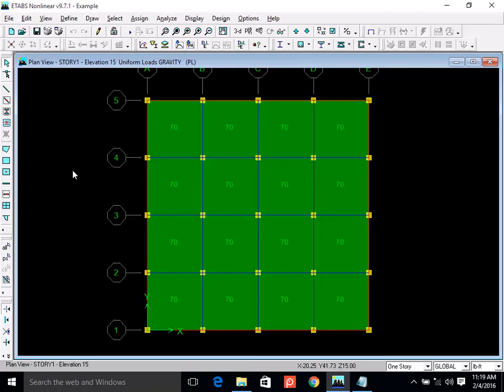You calculate the partition load, you calculate the floor finishes, sum them up on the paper, and you apply the sum here. But it is advisable that you keep them separate, because sometimes you have to make some specific change. If they are combined, then changing becomes a lengthier procedure. So I strongly say keep them separate, although all of them are dead loads.